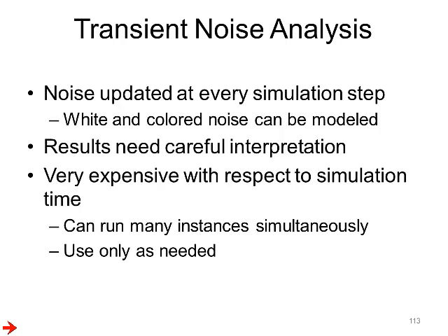This noise waveform, so to speak, is updated at every simulation step, and it's quite straightforward to model white and colored noise. However, one has to be careful to interpret the results, and more importantly, it's extremely expensive with respect to simulation time. One thing you could do is if you have a server farm, you can run many instances simultaneously and average the result. But this is not useful for design iteration, I guess.